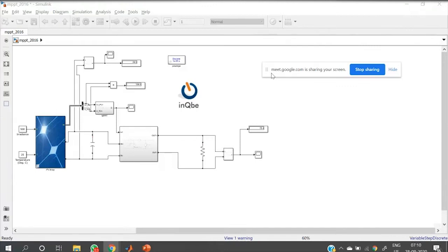That's a complex thing. In partial shading condition, we cannot lift the voltage to a higher level. At that time, the main suggestion is to avoid partial shading and limit the number of series cells. Use the panels in parallel to overcome the partial shading issue. Then you may have to add a converter, which is another challenge. That means series cells can be made parallel to avoid partial shading.